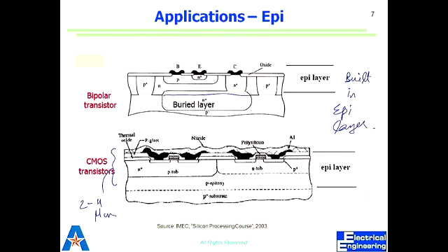What's the difference between N and N plus and P plus? Heavily doped. I see. N is lightly doped, N plus is heavily doped. What benefit do we get by heavily doping a substrate? High conductivity. Is that what we always want? Not necessarily. We want charge carriers and we want high mobility. If you have a heavily doped channel, you have much less mobility. But you need carriers in the source and drain, collector or emitter, whichever the case. Collector, emitter for BJTs and source and drain for FETs.